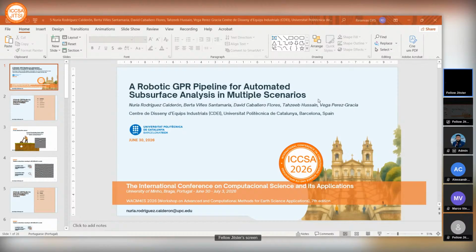Again, with all those hyperbolas detected with computer vision, we created this kind of integrated program where you find a peak response in yellow. It means that there is a strong hyperbola in that place. We did a circular survey, and we excavated the tree to find the roots. What we found is that the zones with higher amplitude, meaning more yellow, are the zones that had more roots when we were excavating. So again, the GPR proves to be a good sensor to find things that are underground.